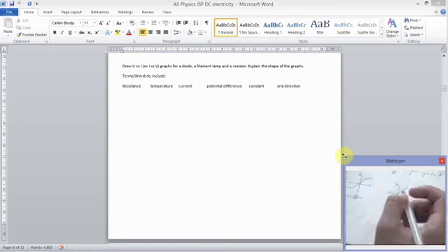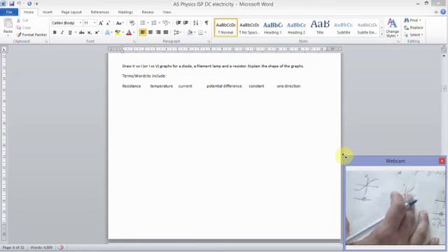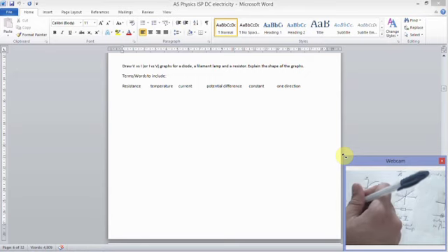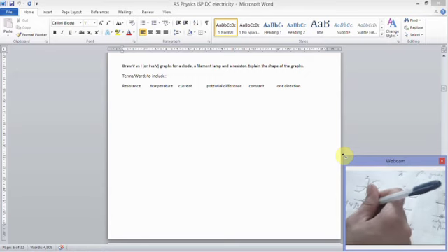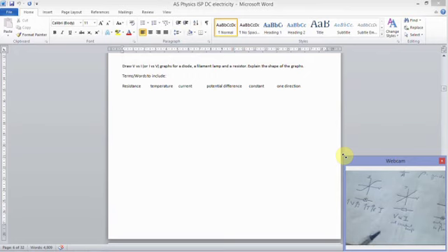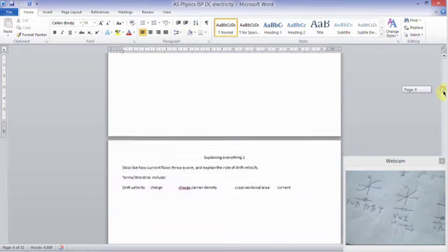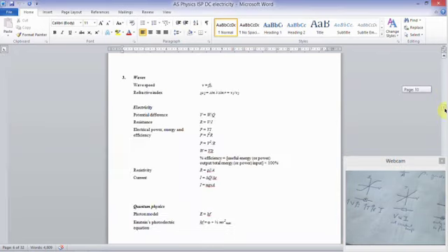You need to be able to explain that idea. As voltage increases, current increases, temperature increases, therefore resistance increases, so current levels off. That's your thought process for that. Excellent, so that's the explaining everything task done. We might as well jump straight into the questions, which are further down. Let's get straight into these.